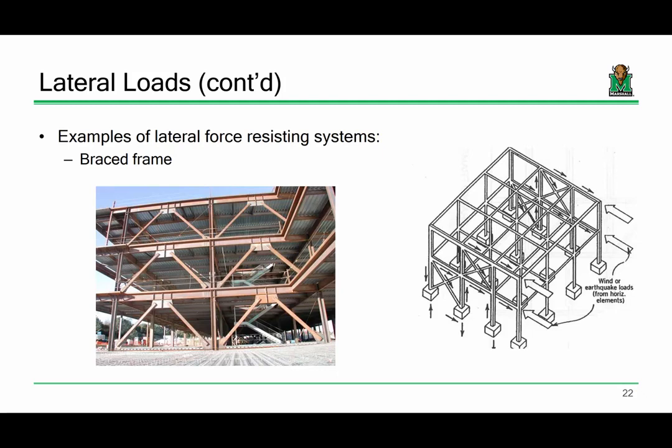Now, we really have 2 primary systems that we use. We have braced frames, which is actually inserting bracing elements into the system. So when it's all said and done, braced frames behave a lot like trusses. Basically, once you determine your equivalent wind pressures on the building, you take those wind pressures and that whole tributary area concept, remember that?